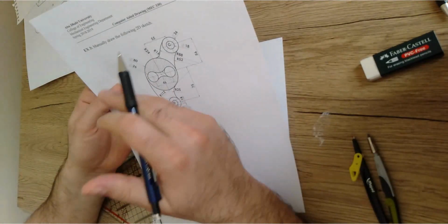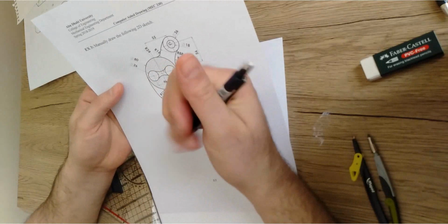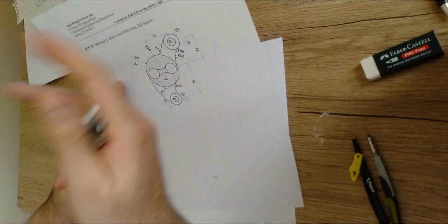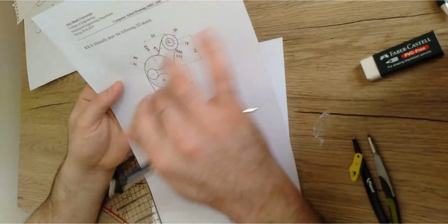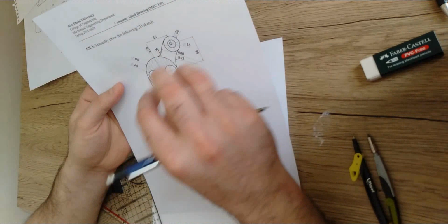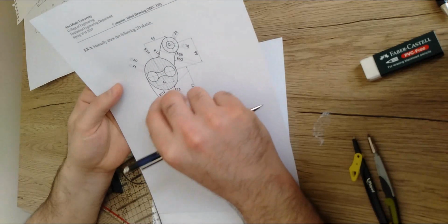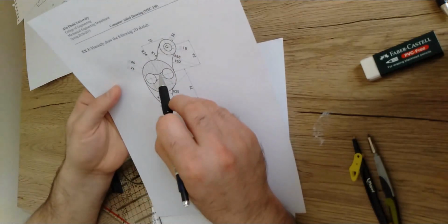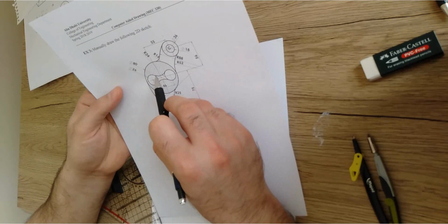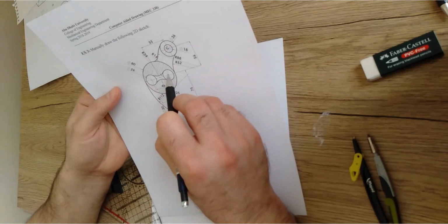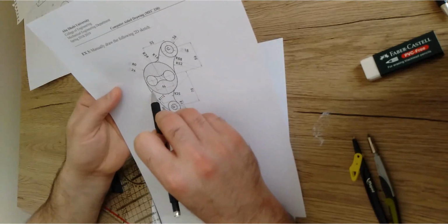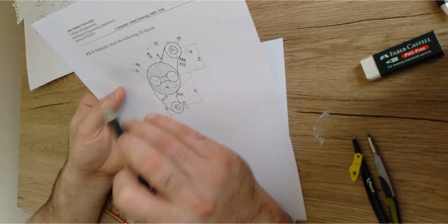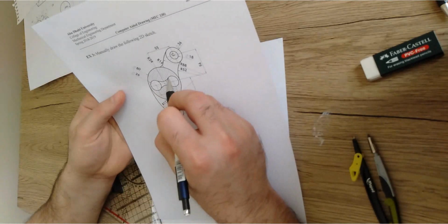The key idea here, because we do have lots of curves in this case, is different than the previous example, because in the previous example we already had two objects and a curve between them. But here we have lots of curves and circles, so you have to make sure what are the objects that the curve is already tangent to. Like for example, this curve is already tangent to these two circles. So I'm gonna use their centers to locate the center of this curve.